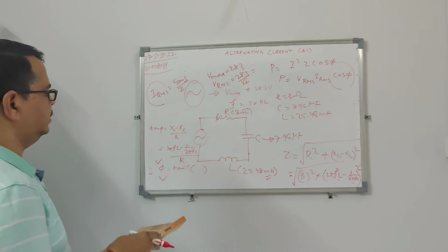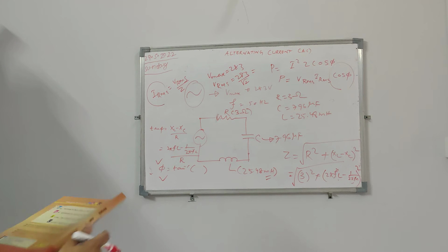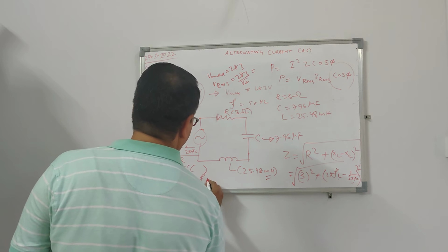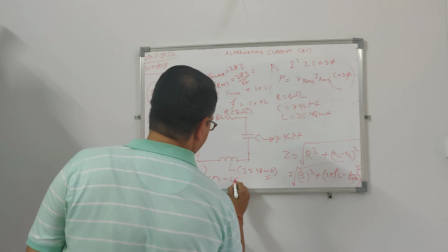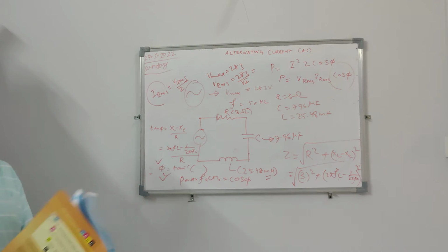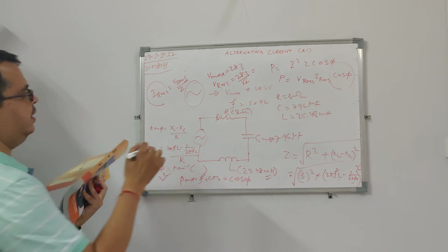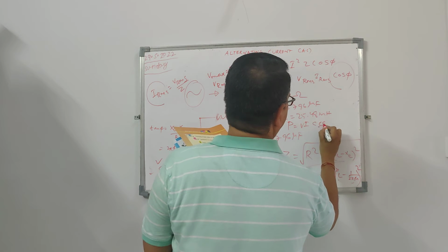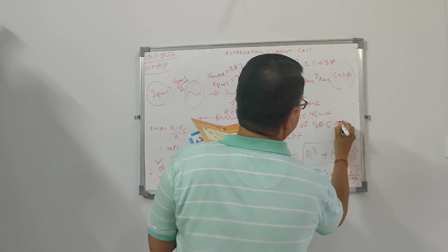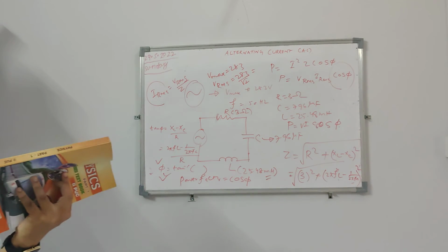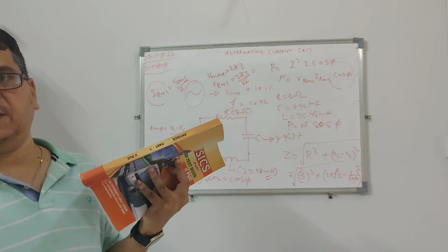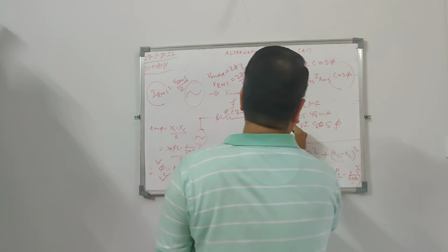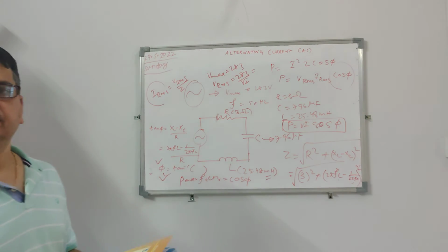And the fourth part is: what is the power factor? You know phi. Just remember that power factor is nothing but your cos phi. Very important. Power factor is cos phi because finally I have derived that P is equal to V I cos phi. Because it is cos phi, I am telling that a purely inductive circuit or purely capacitive circuit carries wattless current, because the phase angle is 90 degrees. So this term is important. In LCR it will be cos phi.